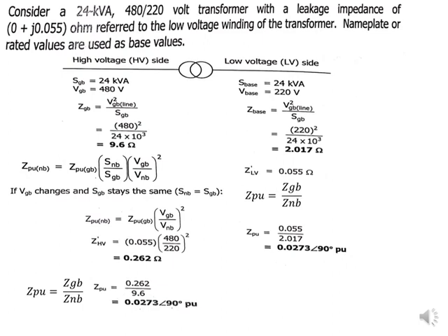as long as it is that same transformer, your impedance across the transformer is the same. Either you are on the high voltage side or you are on the low voltage side, your impedance of your transformer is the same. And this becomes important as we go about doing all the exercises that are going to follow.